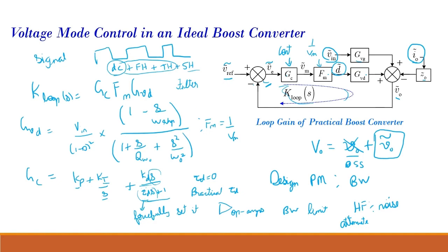So that is why this tau d of s plus 1 acts like a filter. It will remove the high frequency components. Now, if tau d was 0, it means it will act instantaneously. It will act very, very fast because the bandwidth is very high for the derivative part. If it has to act very fast, it should act at very high frequency. But now we want to limit that frequency of operation so that the noise doesn't affect it.